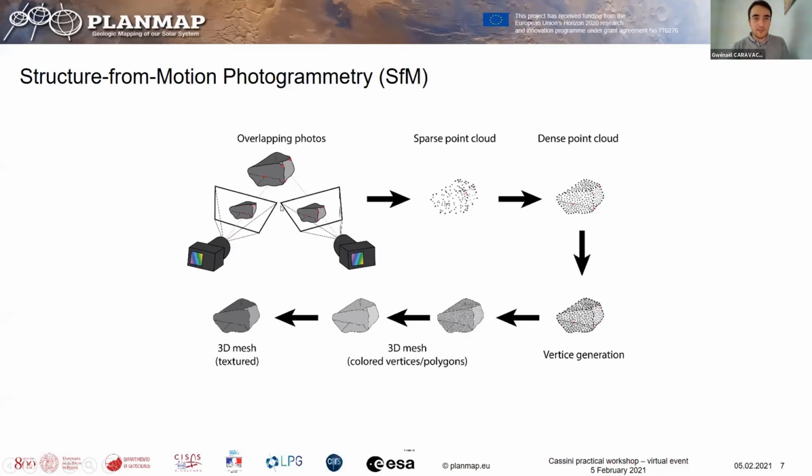You can see that these points are located in very different positions on the 2 photos. This is very important to understand, because it is the difference in position of these specific points within 2, 3, 4 or more overlapping photos that will help the software to reconstruct the 3D shape of the object.